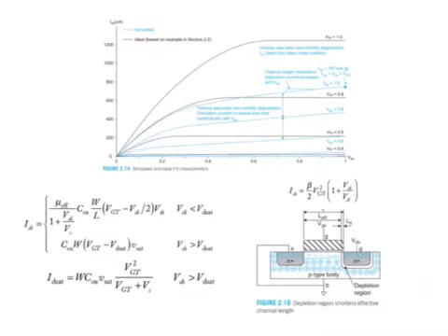And so to get a visual perspective of what happens, we have this graph here that shows the IV characteristics. The characteristics plotted in black are the ideal or long channel IV characteristics of the MOSFET, and the curves plotted in blue are the short channel IV characteristics that arise due to the effects of velocity saturation and mobility degradation.